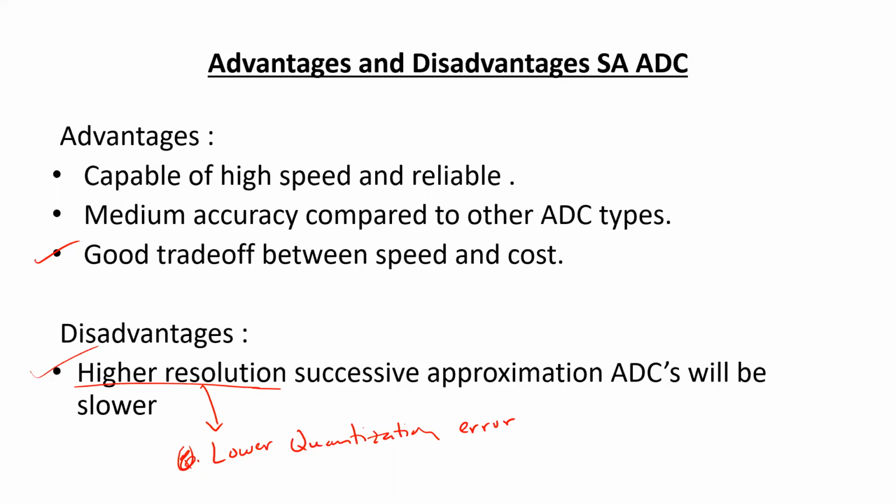So you are going to check whether the resistor that you want to measure is giving you the desired result or not. So in most of the cases that is the case, that you want to determine whether the resistors that you have manufactured are giving you the desired value or not. So you compare it with a standard resistance. Okay, by varying the value of the standard resistance, you want to tune to obtain a balance condition to check whether that particular resistance is giving you the desired result or not.